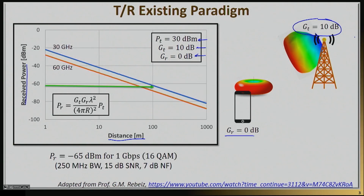A lot of times you will see gains in cell phones down to -6, -7 dB, and so on. But nevertheless, let's assume it's about 0 dB. And then I'm assuming that I need to receive roughly a 16 QAM modulation scheme, which we did cover in this class. And for that one, for a 1 gigabit per second data rate, I need to receive roughly -65 dBm.